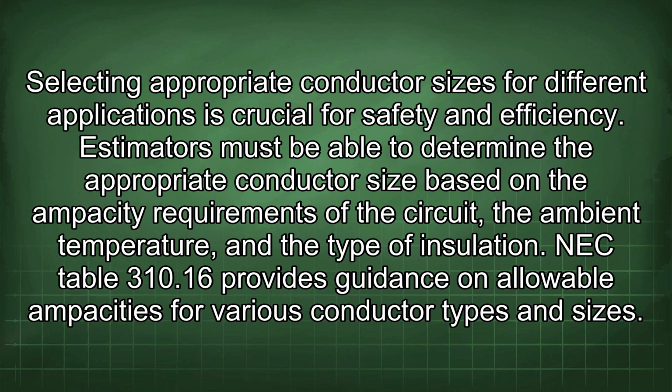Selecting appropriate conductor sizes for different applications is crucial for safety and efficiency. Estimators must be able to determine the appropriate conductor size based on the ampacity requirements of the circuit, the ambient temperature, and the type of insulation. NEC Table 310.16 provides guidance on allowable ampacities for various conductor types and sizes.